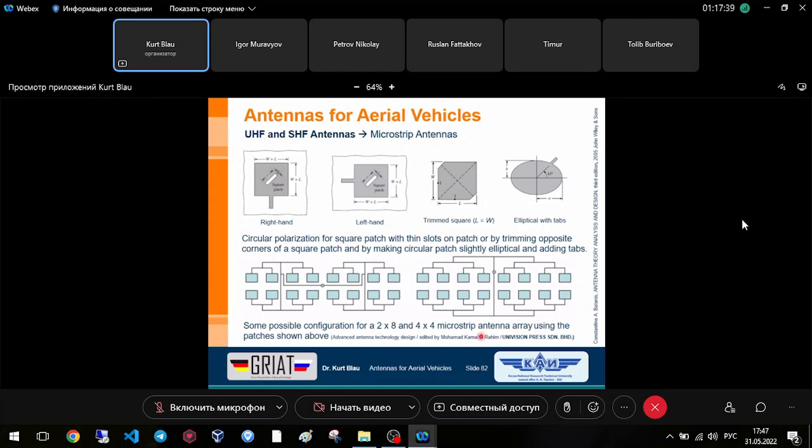You can do it in this way, and to make the same phase difference between this line of elements and this line of elements, you can use only a single offset. This means if you feed it here, all feeding points are center points, and only the main center point, which is not here in the middle, has an offset. If the center point is in the middle, the radiation goes perpendicular to this plane where the elements are arranged.